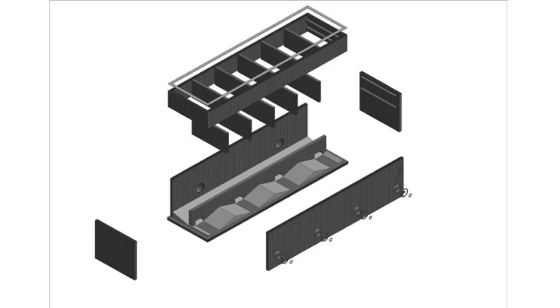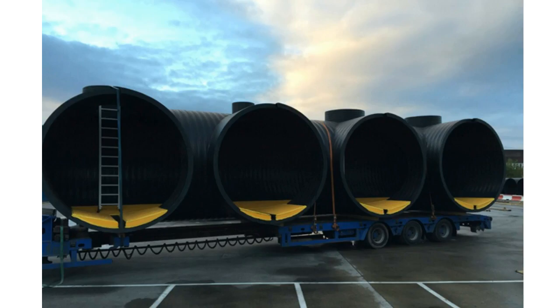Down here we have a tapered area, so sedimentation and particulate can be flushed out by these flush ports at the very bottom. Another configuration design is a manifold, again showing the flexibility in our design and the options we can provide. In this particular one, the yellow shows where we've installed channelization of low flows, as well as an access point for the FRP ladders.